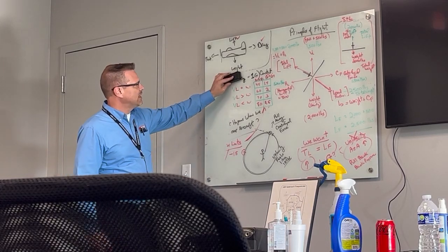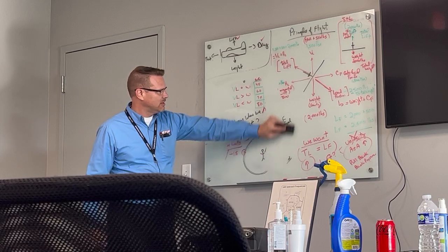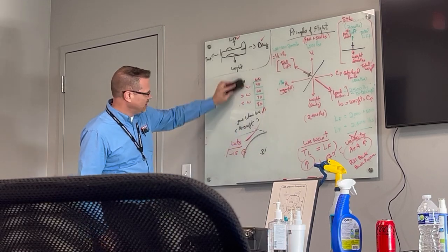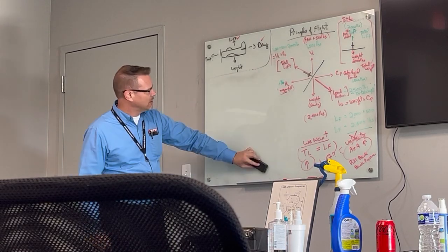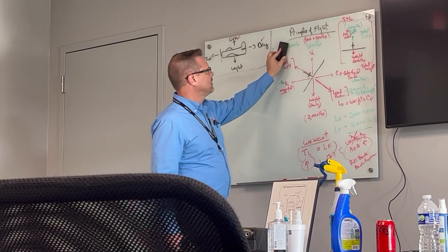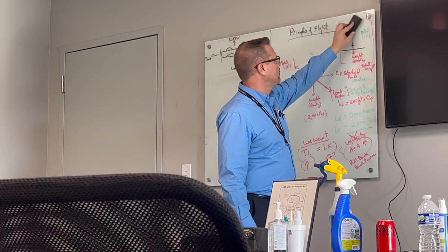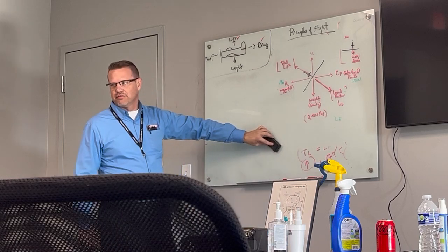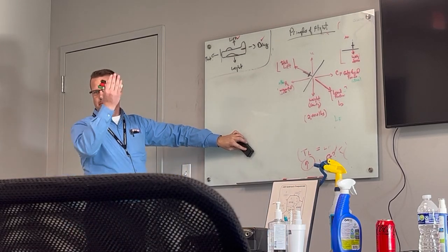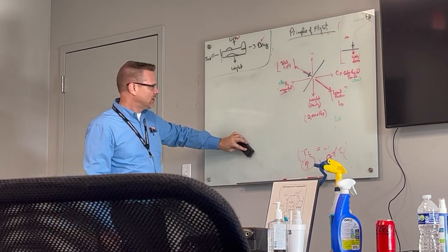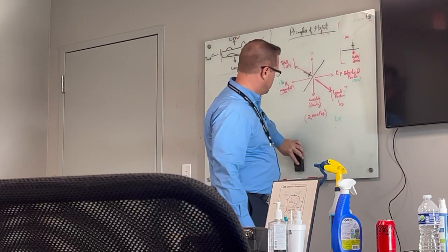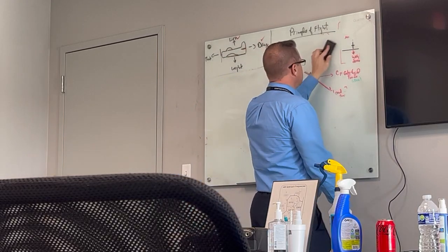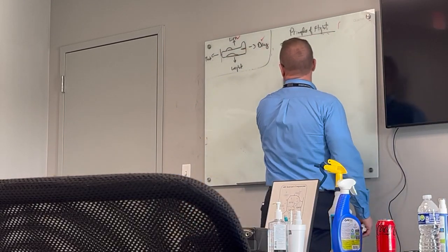Planes do not like to be stressed in a negative G fashion. That's why, you look at fighter jets, they roll onto their back before they dive, and don't push over on the nose into a negative G dive. They'll roll onto their back and they'll pull positive G, right? Because you can pull a lot more positive Gs than you can negative Gs.